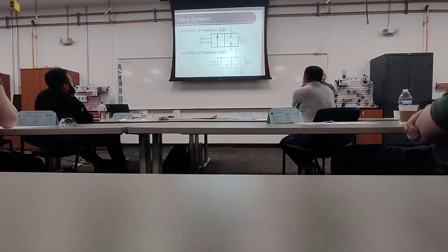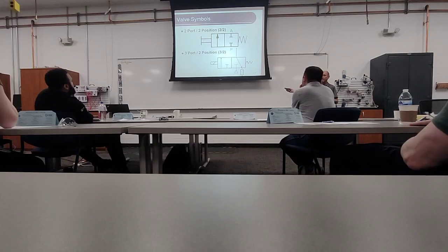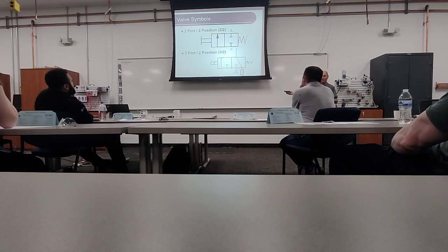So air blow-offs, air motors, air grinders, and then a lot of times we'll use them for media valves, which is fluids. So you either want to let the fluid flow or stop the fluid from flowing. All right, this one is a 3-2 spring return. What does that mean? Electric, purely electric, not electrically air piloted.